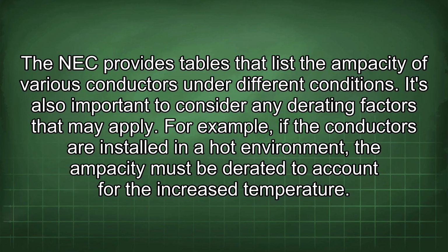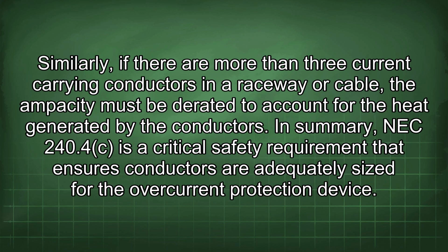For example, if the conductors are installed in a hot environment, the ampacity must be derated to account for the increased temperature. Similarly, if there are more than 3 current-carrying conductors in a raceway or cable, the ampacity must be derated to account for the heat generated by the conductors.